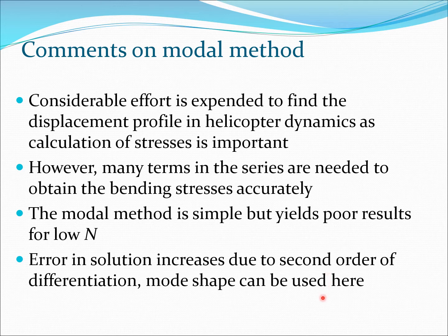So one of the ways to enhance the modal method would be to use a better function. For example, the mode shape can be used, but typically mode shapes of the non-rotating beam can be used, or even a rotating beam can be used if it is possible.